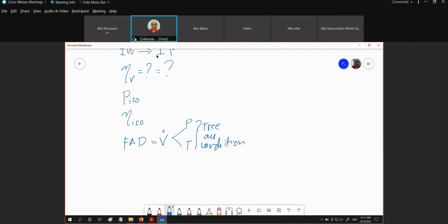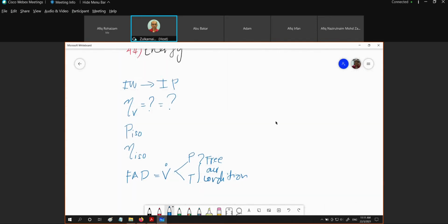Is there anything that I left out? Can you remember, or you can remind me? Is there any parameter that we looked at that we haven't touched on? Maybe as additional, we can look also at what we call the mechanical efficiency. The losses during the transmission of work from a prime mover, where maybe we can use an electric motor or engine to drive the compressor. So it's involving the mechanical efficiency. Maybe we can also consider the motor efficiency, because of the electrical motor and so on.